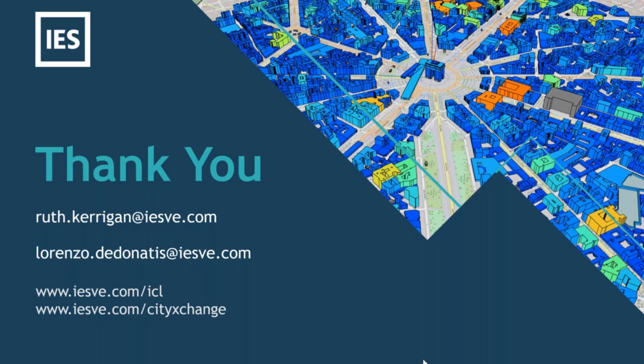Okay. Regarding the U value of the double glazing, it was taken from construction manufacturers, and we selected the double glazing because we found a possible solution in Ireland for replacing existing windows without touching the frames, retaining the existing frame and just replacing the window pane.